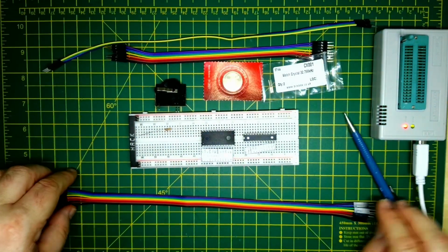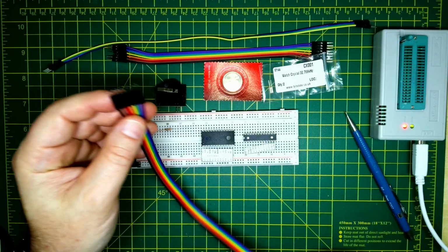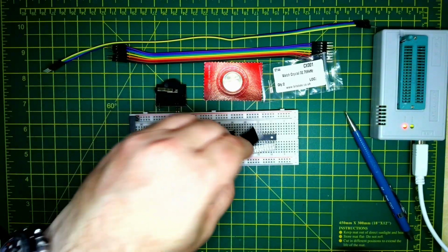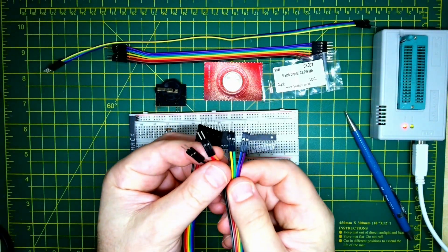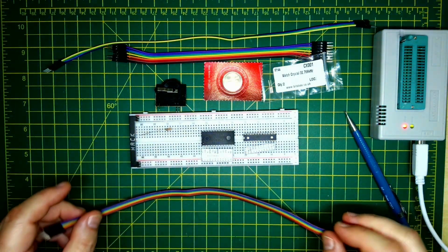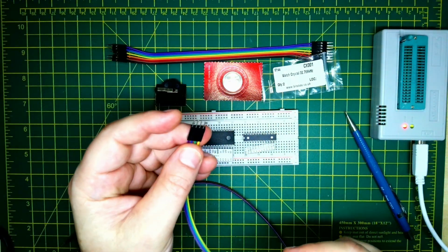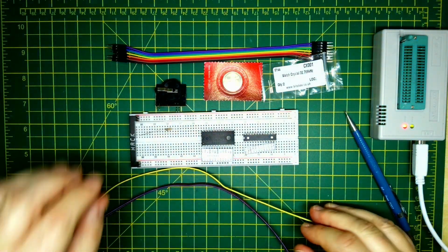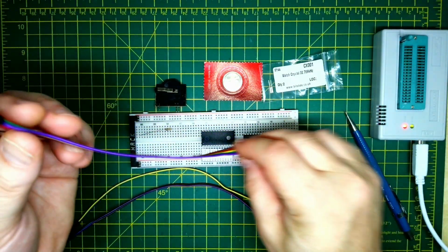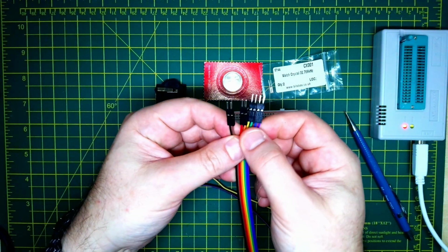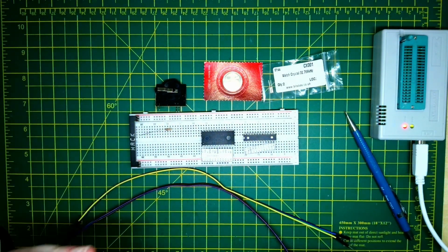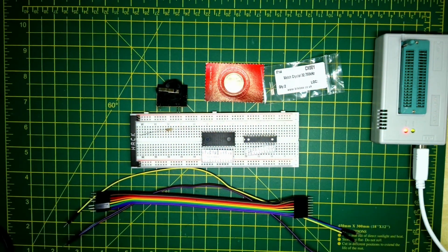Button cell, and then I've made up some cables. There's an 8-way cable for the addresses coming in, with sets of 2 to plug into the bus rails, and this is the A0 to A3 address lines. Then we've also got the data bus, which will go into the RTC chip, and then we've got sets of 2. I made up those cables as well. All we need to do now is put on the chip labels and program the PLD. I'll just show you the PLD configuration options first.